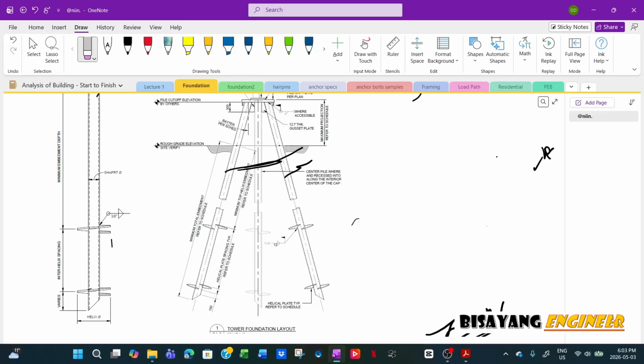But with this one, all you have to do is bring in an excavator, then attach the pile. I already posted many times about this on my page regarding screw piles and the different pile drivers. All you have to do is attach it to any equipment they have, like a bobcat or excavator, and then install the pile.